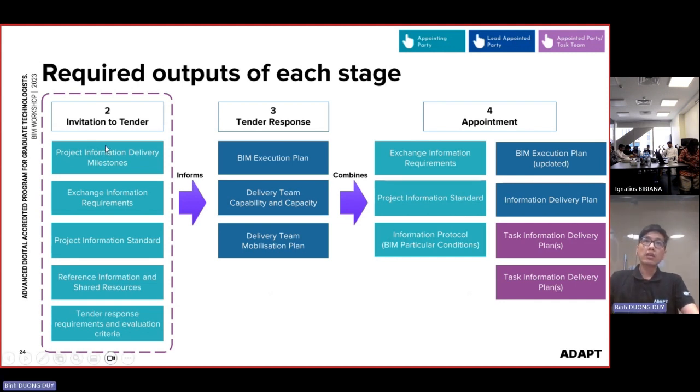After that, the client will consider the profiles of the companies who attend that tender, and they will give appointments. After the appointment has been decided, the BEP will be developed in detail. That is called the BEP after appointment, the post-appointment BEP. Along with this, we also have to provide some information delivery plans.